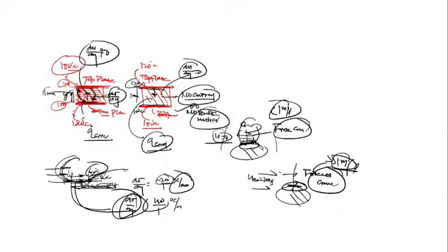For conduction there is Fourier's law. Q is equal to, I will discuss it in the next lecture, minus k dT upon dx. It's Fourier's law for conduction. So Fourier's law says the rate of heat transfer via conduction is proportional to the temperature gradient. Is this clear? At the wall, either free or forced, the heat transfer via conduction is always there. But since the rate of heat transfer via conduction is proportional to the temperature gradient, and the temperature gradient will increase via fluid motion. Is this clear?